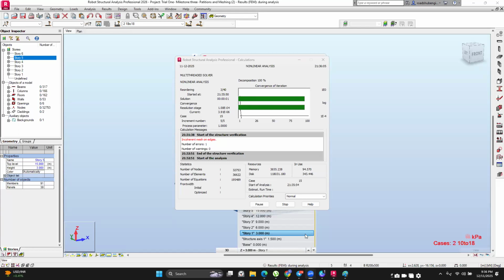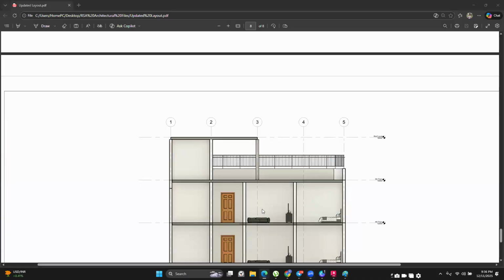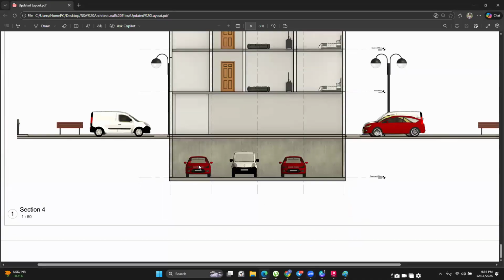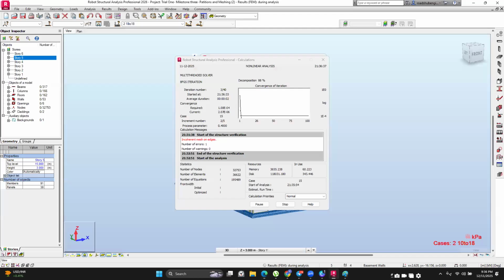I think you got it wrong, engineer. If you look at the purpose of these specific walls that we have, this is our basement here. We are not filling the basement with soil. The soil is on the outside, so the soil is pushing the basement wall inward. This wall is to resist soil from going into the basement. Understood, thank you. Yeah, the basement is actually extra parking space.